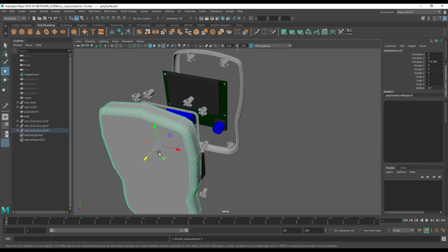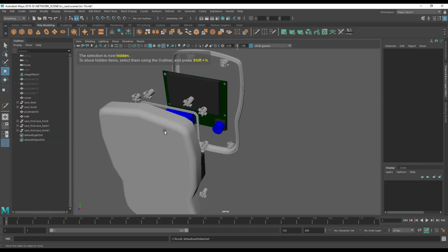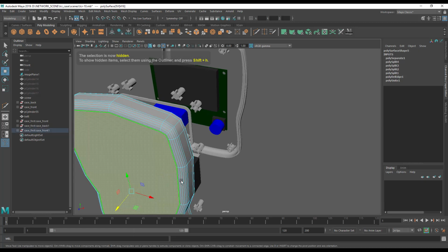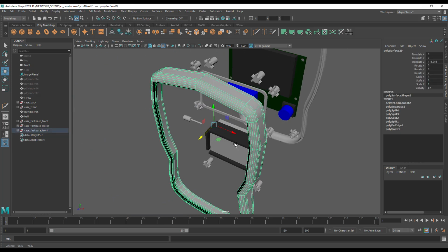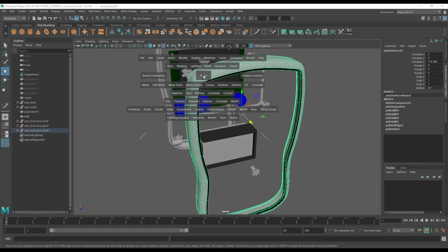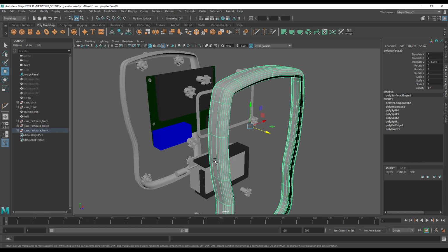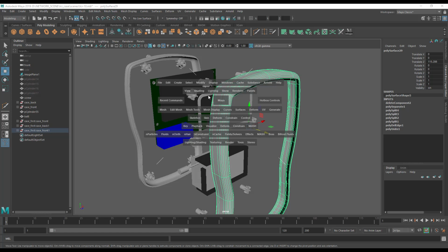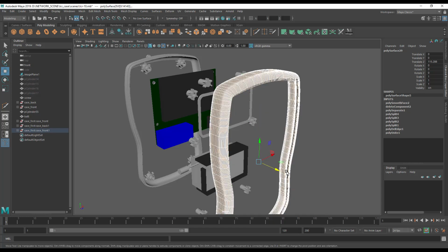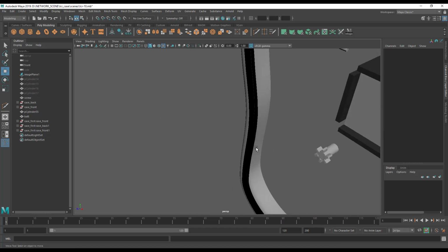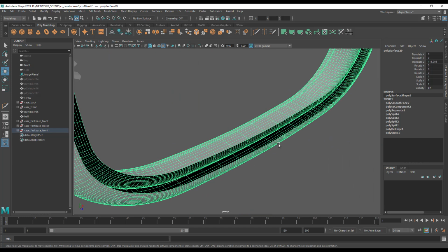And same for this one. So keep a copy of it, hide the copy, and just remove these 2 faces, 1 and 2. So this is just really one of the limitations of using Maya. It, in most cases, doesn't turn out to be too big of a deal, because say I did redesign this thing in between these parts, and it took me 10-15 minutes, it's not the end of the world. We're looking for convert smooth mesh preview to polygons. Then of course we'll need to fill them in and recut the booleans.